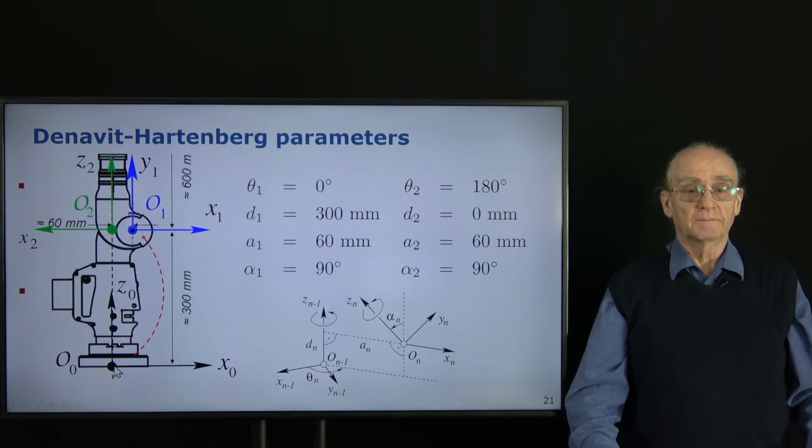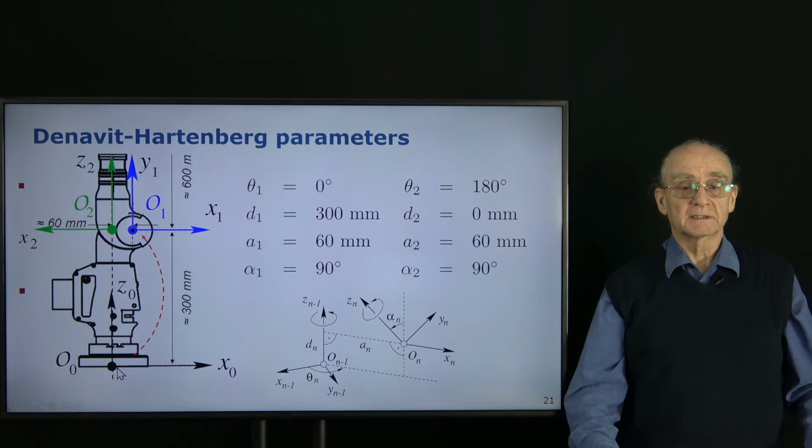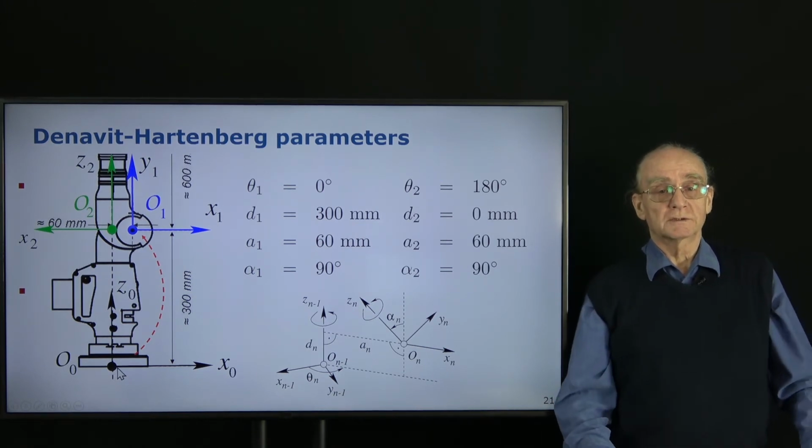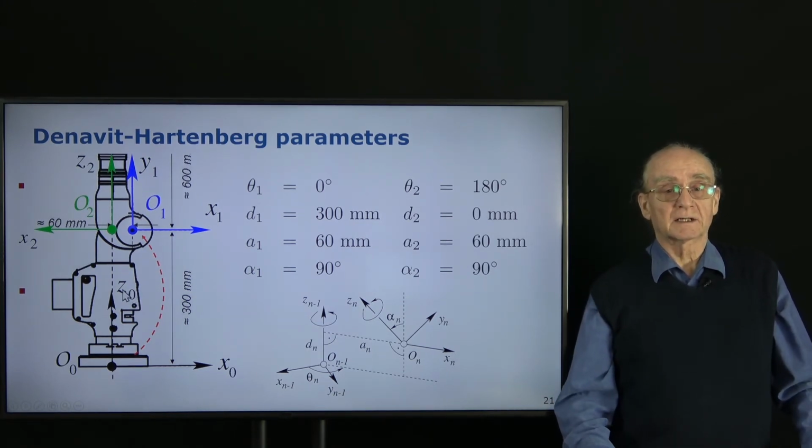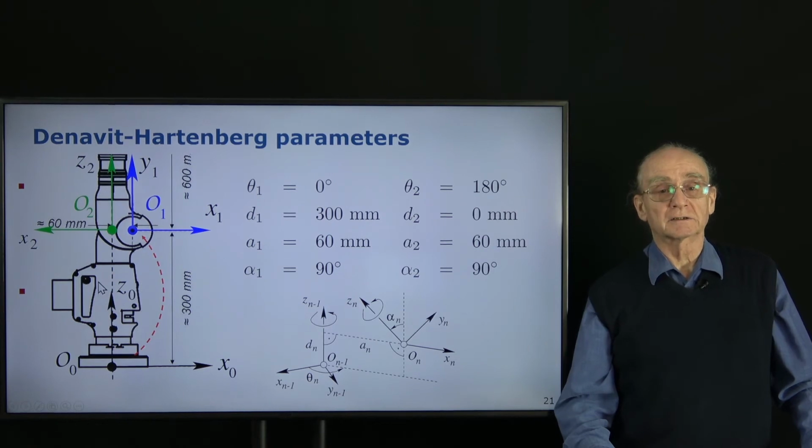We start here at the ground of the table where the robot stands, and I assume that this can be rotated. That means the coordinate system S0 is chosen so that the z-axis is actually the first rotation axis along which we rotate at the beginning.